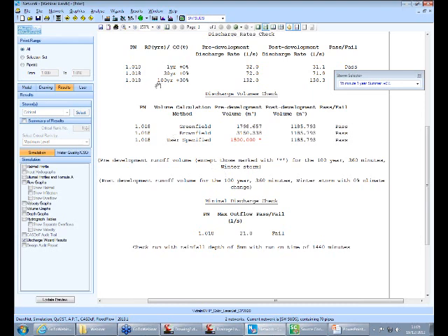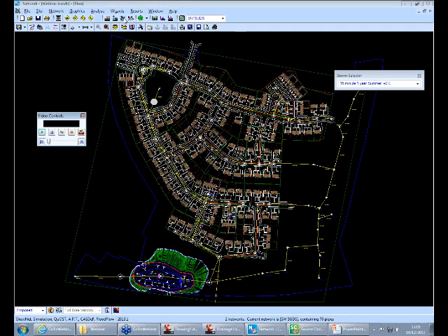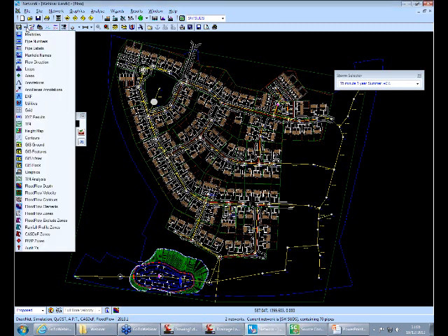The next and final step I'd like to show you is to extract all of this information that James has produced in the 3D format. So how do you now extract that back into Civil 3D or back into full AutoCAD? Looking at the plan view, what you see is what you get. From the view options, I can switch off unnecessary layers of information, and I really just want to focus in on the pipe network and then bring that in as a 3D entity across into AutoCAD.